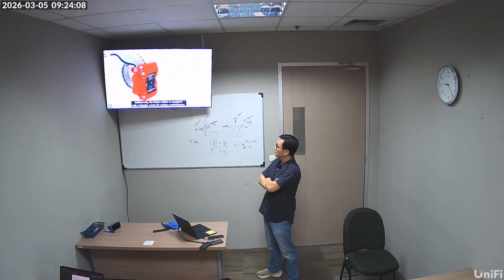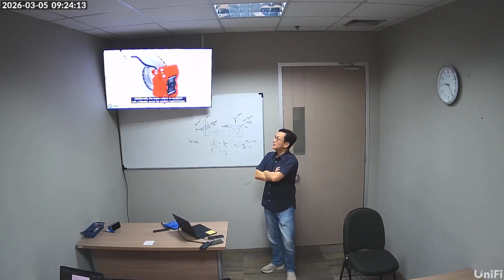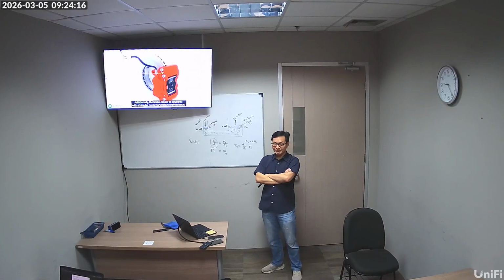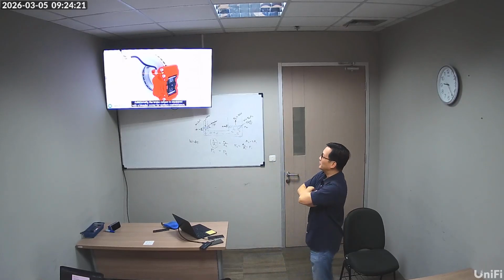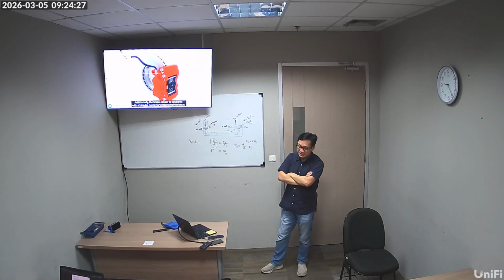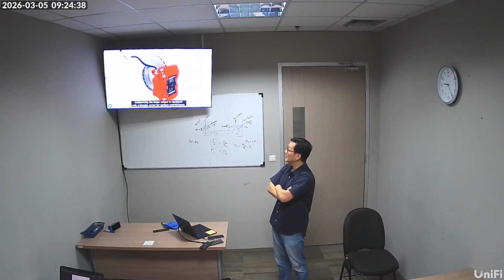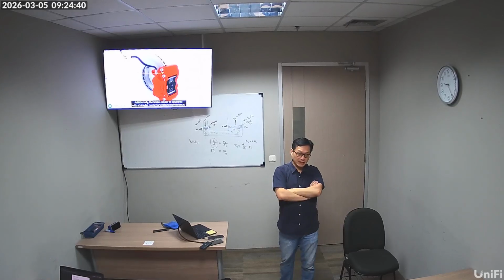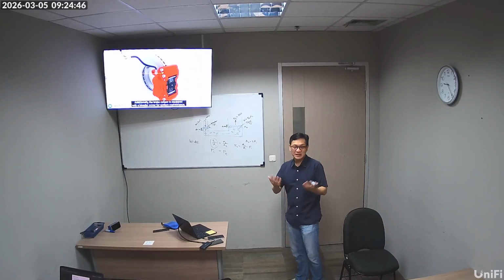Additionally, the brake caliper is equipped with a bleeder screw for system maintenance. Anybody knows what it is? The bleeder screw? You would know. It's to remove the air and flush the brake system. Sometimes there is no air, but there is water mixed in with the brake oil, the hydraulic oil. So it is something that people underestimate, that the hydraulic oil needs to be flushed every 50,000 kilometers or so.